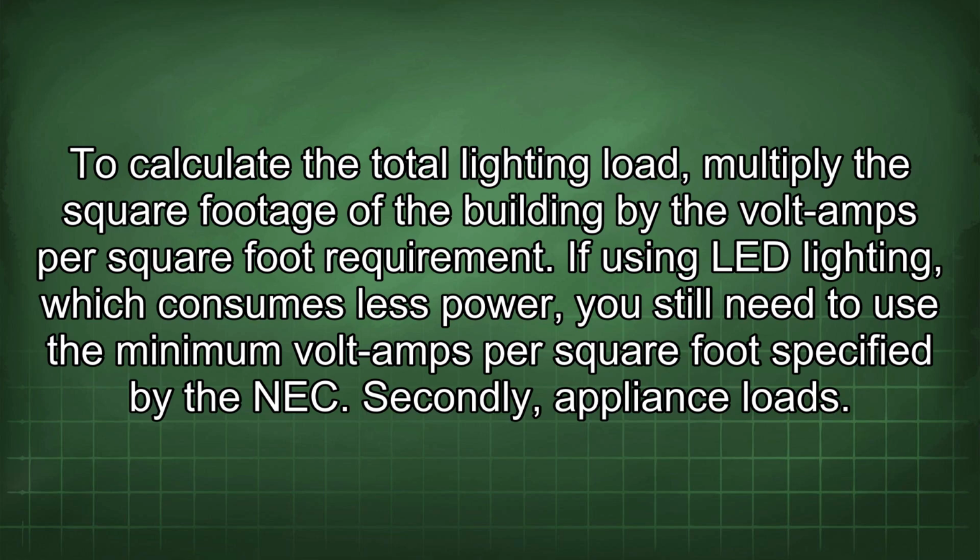To calculate the total lighting load, multiply the square footage of the building by the volt-amps per square foot requirement. If using LED lighting, which consumes less power, you still need to use the minimum volt-amps per square foot specified by the NEC.